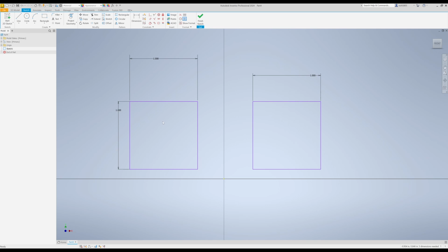So first of all, let's start with the fillet tool. The fillet tool is right up here. It says fillet. You can click on that, and it pops up with a little box. It's starting off at 0.125 inches right now, and let's stay with that for a second. If I come over here to this corner, I can click on that, and it will add a fillet. And a fillet is basically just a rounded corner. I can click Escape, and now we have a fillet right here.